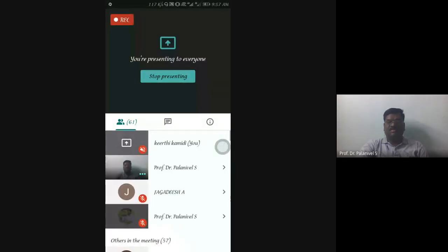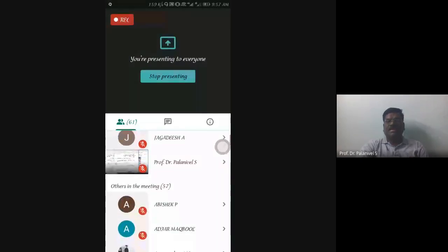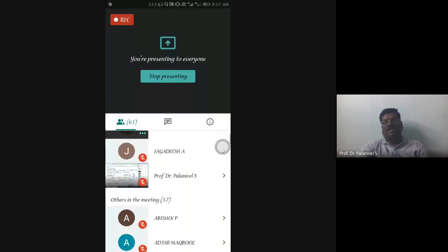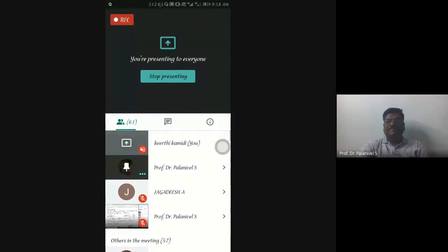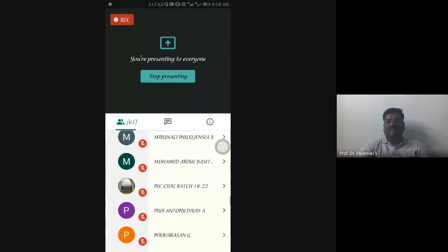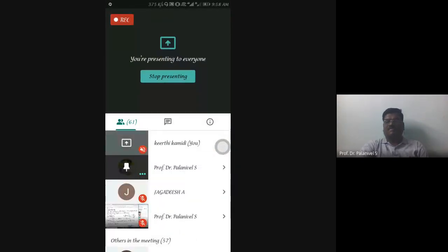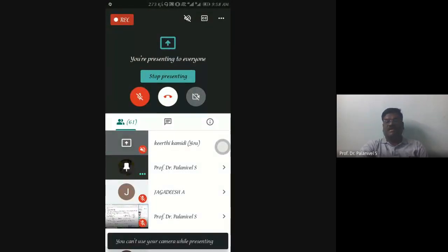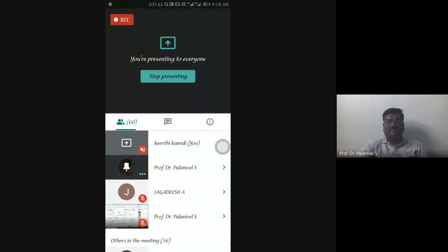Now, using this deflection equation and slope equation, we can determine the deflection or the slope at any point along the length of the beam. We are interested in the free end of the beam, where the deflection is maximum. It is obvious. Also the angle of rotation, in other words the slope, is also maximum at the free end. We are curious to know those maximum values.